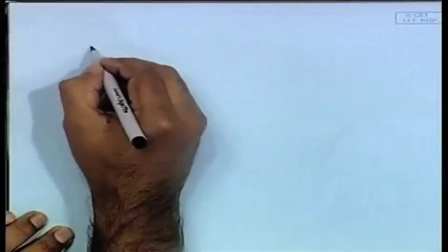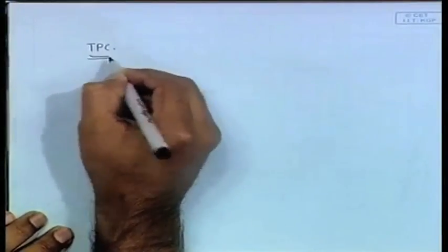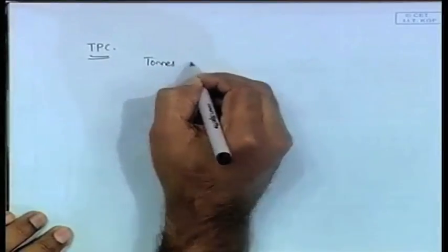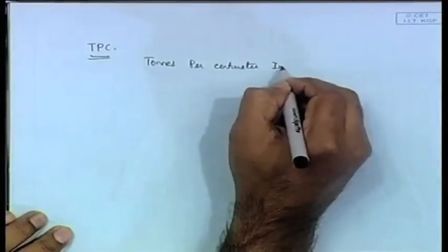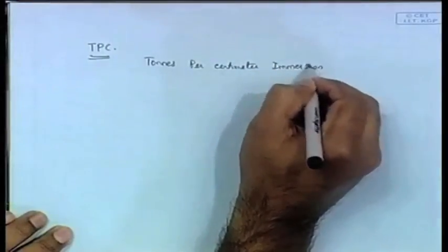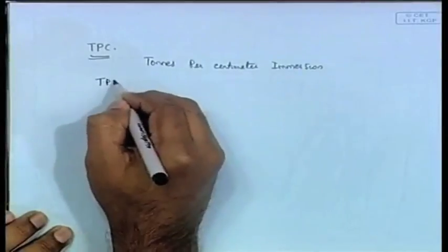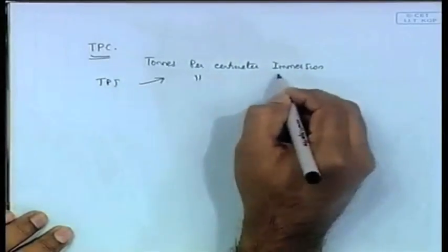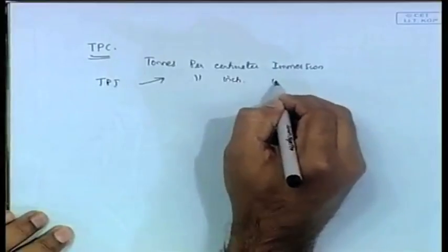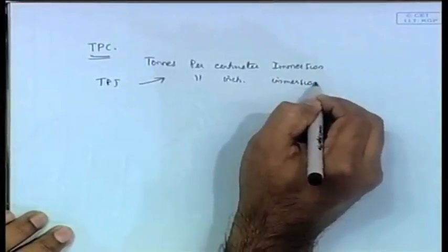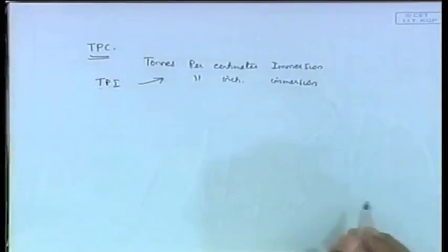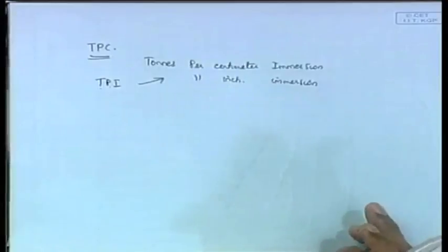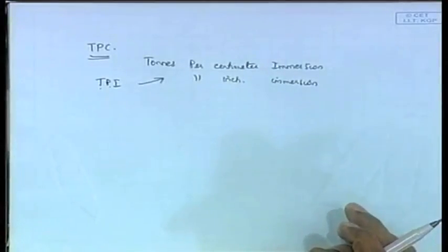Now, one additional thing, another term that we usually use is TPC. It is defined as, sometimes it is called TPI, it is actually the same thing, tons per inch immersion, TPI tons per inch or tons per centimeter, not the same thing, but it is different dimensional systems.